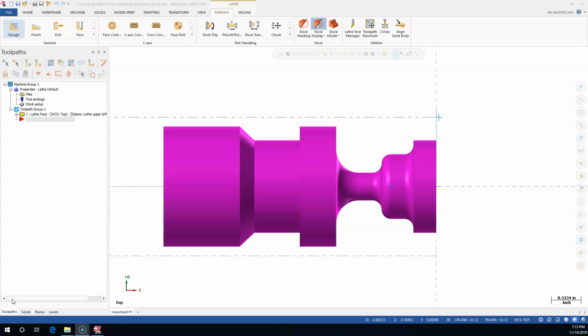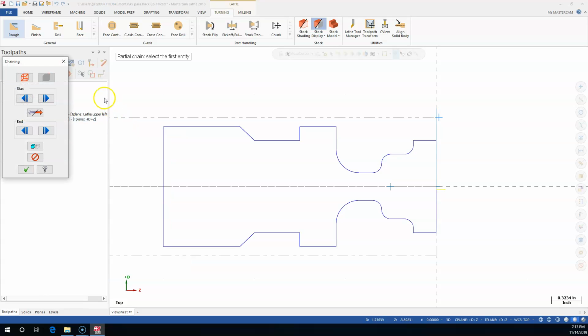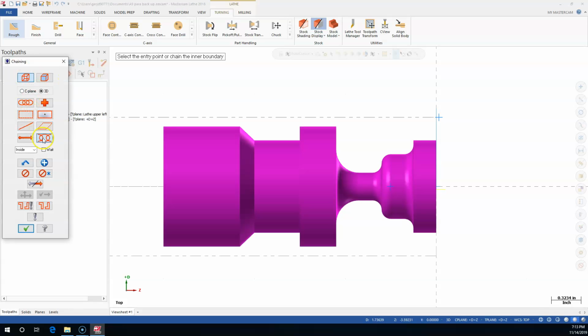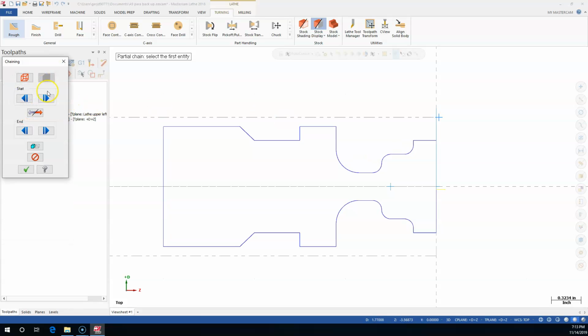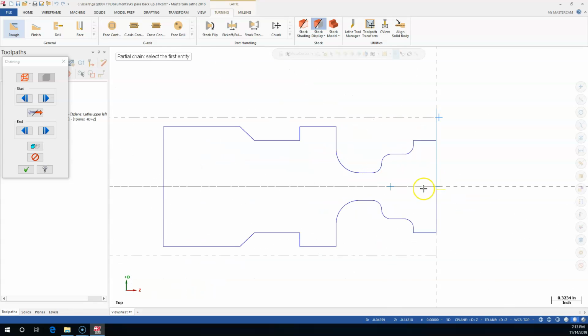And then pretty much the same thing that I always do when I'm working in a solid. Lathe toolpath, rough, and it changed over from wireframe, and I was still trying to select my part as if there was wireframe geometry there. We need to switch over to solids, and then now that finds the cross section through the center of the part, or actually where the top plane intersects the part. So that was the reason why shifting this front to back had those negative effects.